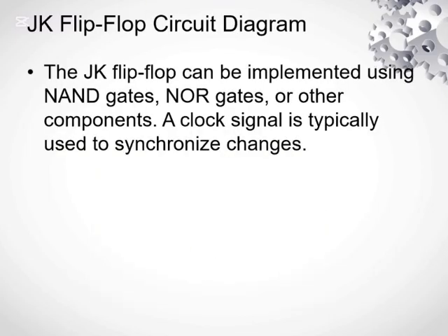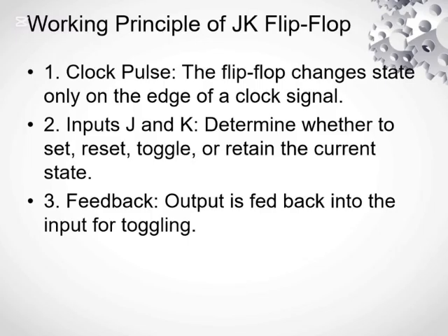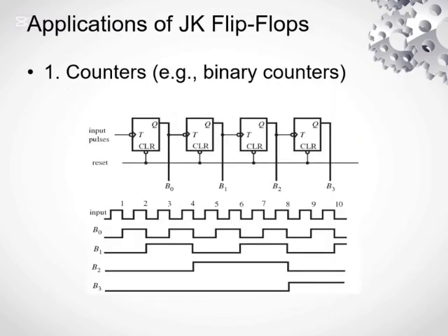So the working principle is basically that it changes its state only at the edge of a clock signal. The inputs decide whether it is set, reset, toggled, or retains its current state, and it also gives feedback through the output. So, applications of JK flip-flops.